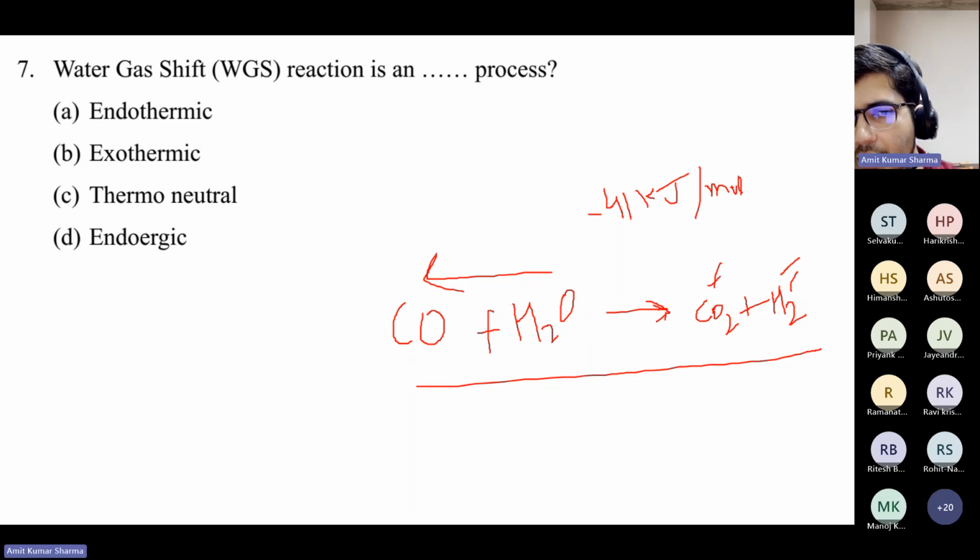So basically, your outlet gas from the reforming reactor will be higher in steam and CO, so hydrogen yield will decrease. Your aim will be to eliminate the possibility of the reverse water gas shift reaction. The water gas shift reaction is good, it is favorable to you, but you want to avoid the reverse water gas shift reaction.